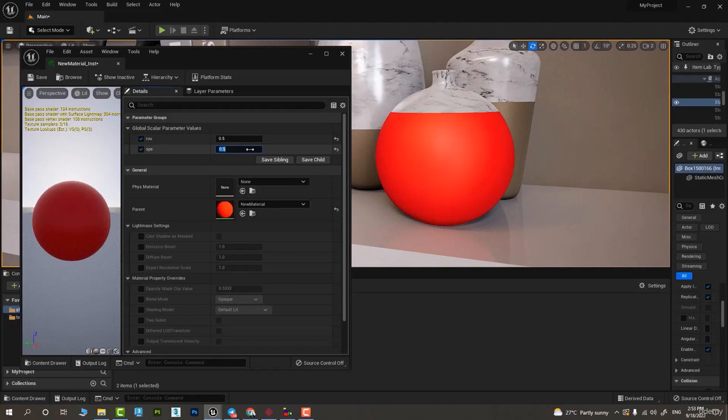If I put a small value like 0.1, it's gonna have less effect, and if I put 1 or anything above 1, it's gonna have the same effect. And so if I change the roughness, for example, to 0.02, the object becomes more reflective, and you can see the differences with the specular as well. All right, so remember that any specular value above 1 is not gonna affect anything, so it's going to be the same as having 1 there.